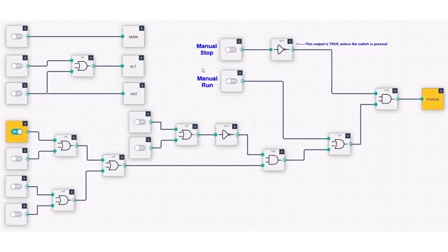And you'll notice that if we have a stairwell detector that's in alarm, it shuts off the purge fan. This manual run will force the fan back on. And this is done, again, using NOT by inverting the state of this point and then running through an AND, and these are ORed together.